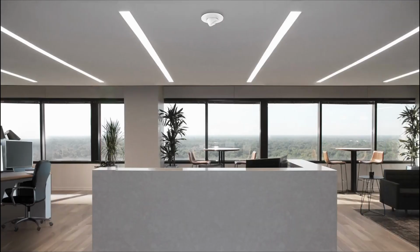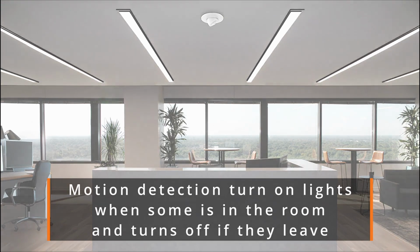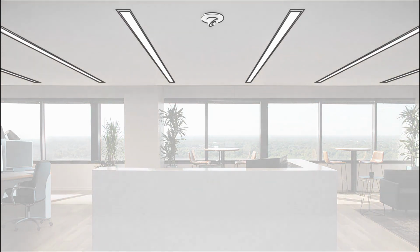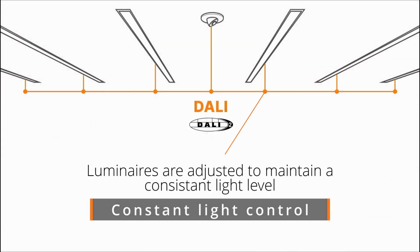In this application example, motion detection ensures that the lights turn on only when someone is in the room and turns off when they leave. Additionally, we will set up constant light control. This is where the luminaires in the room are adjusted to maintain a consistent light level.